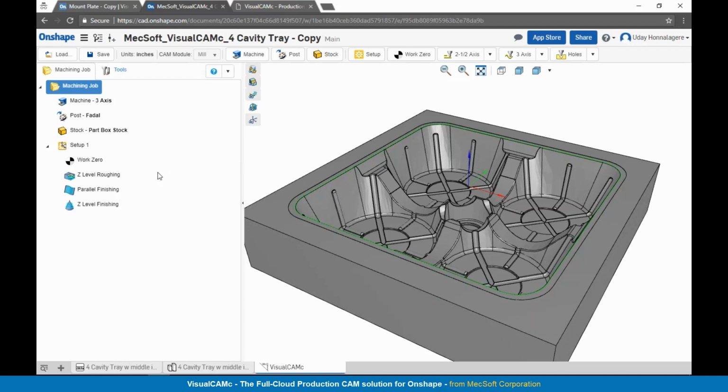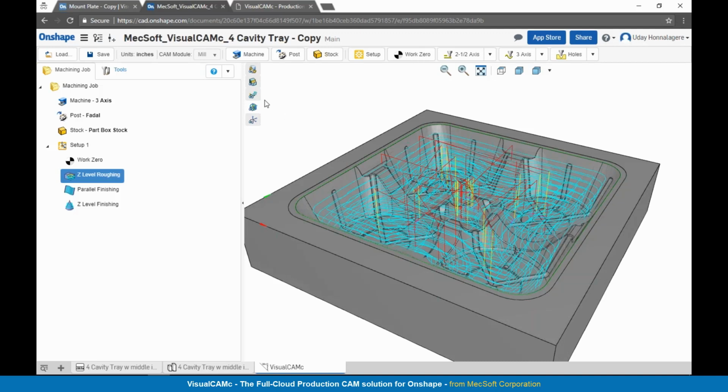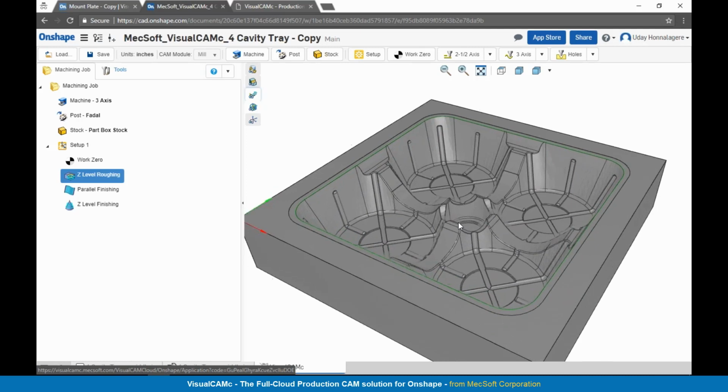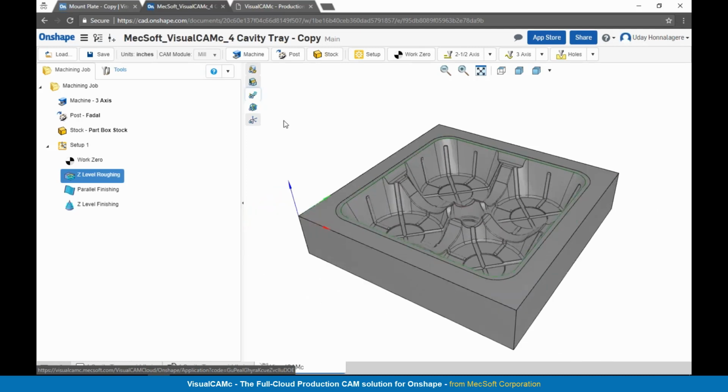So the actual machine model is being created as a solid model. We are working with a third party library, which almost all CAM systems use for the actual creation of the solid modeling cut material model rather, and we will be integrating that shortly. That functionality will allow us to do collision detection with tool holders and things of that nature.